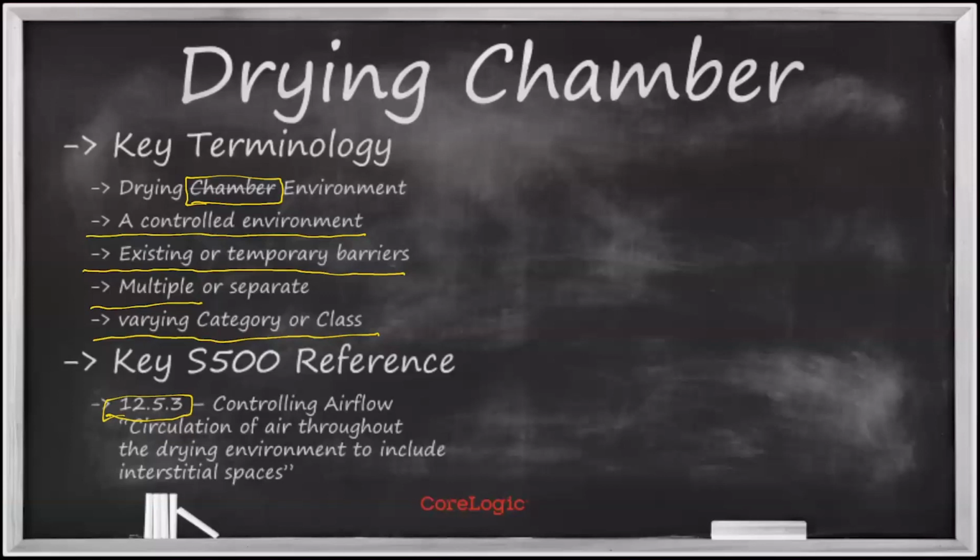And then once I've established that chamber, it's uber critical that I then establish air movement, air flow that is going to reach all of those wet surfaces and ensure that that evaporating moisture can be transported, right? It can be carried. And that's really what air movement is. At the heart of a drying process in your drying plan, the purpose of air movement is to provide transportation. And if I don't provide any transportation to that wall cavity, the water vapor in that cavity is not going to move. Those materials are not going to dry. It's going to become wet and stagnant in an environment where we're artificially warm from our drying equipment. And warm, stagnant, and wet, especially in a dark wall cavity, is a really, really bad recipe.